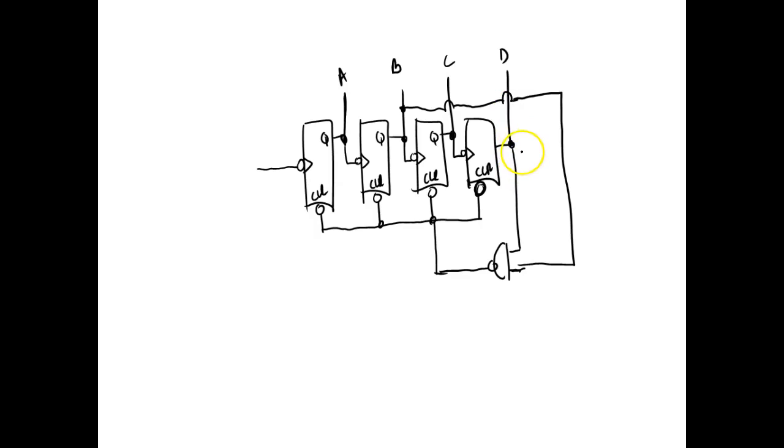So I'm looking at this guy right here. So as soon as this goes to a 1, and as soon as this goes to a 1, we're going to reset the count. And you won't even see this. So we start off counting. Start off at 0, right? Then we go to 1. Nothing's going to happen, right? You understand? This will be a 1, but this one right here would be a what? A 0. So this is going to stay at a what? A high. That'd be a 2. Now this is a 0 and this is a 1.